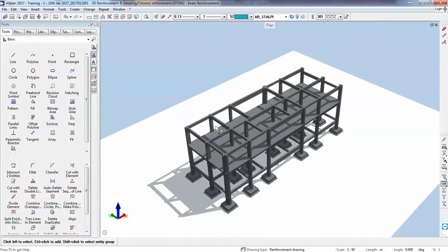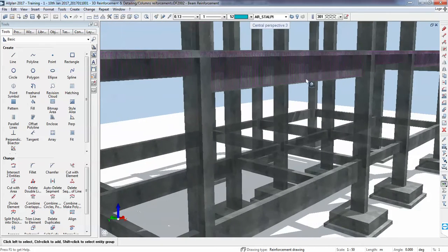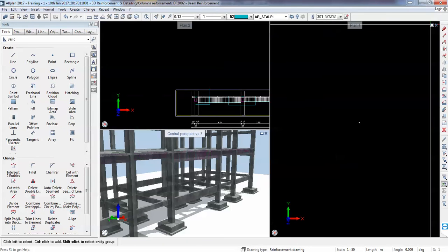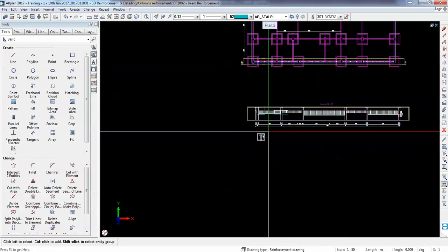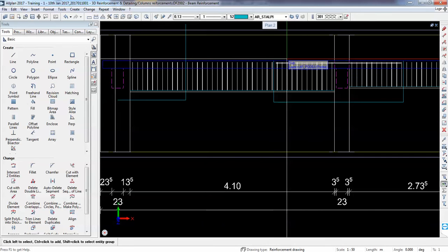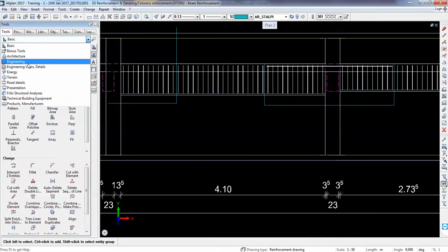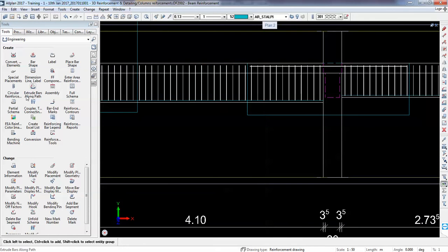Okay, so now if we even hit F4, we'll see we have stirrups in accordance with the concrete cover for all the span. Why I did this at this stage was to have a simplified positioning of the rebar. So I will place the rebar now.